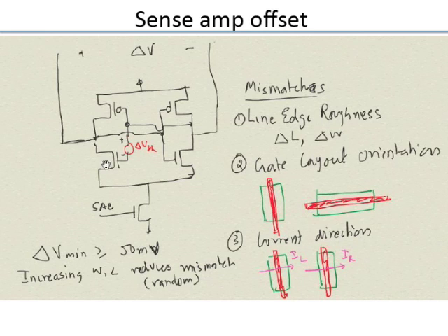The current through it will always be less than the current through this one, because this transistor's gate voltage is higher, plus, whereas this one's gate voltage is minus. So this larger current will also help to pull down this minus even more. It's in the same direction, so it's a positive feedback, and you get the right data value.